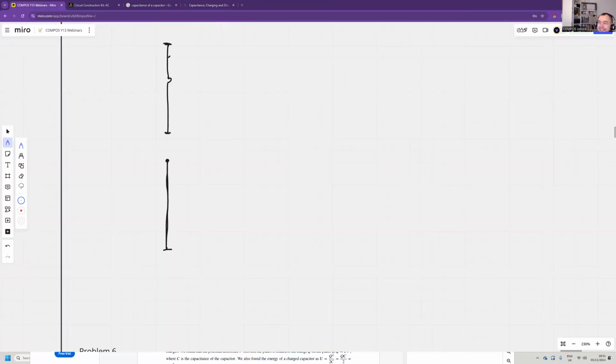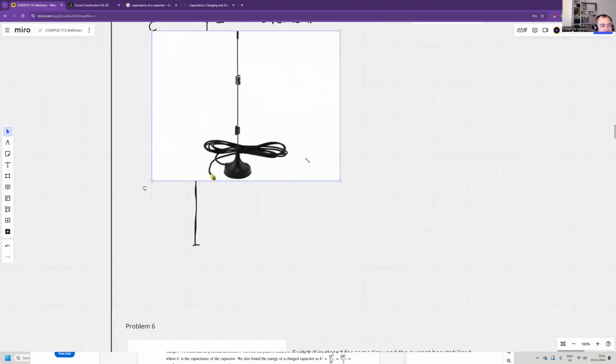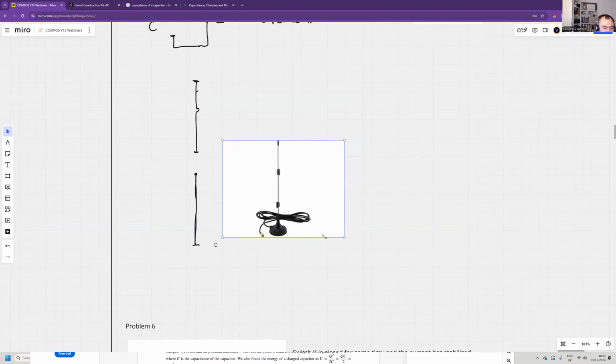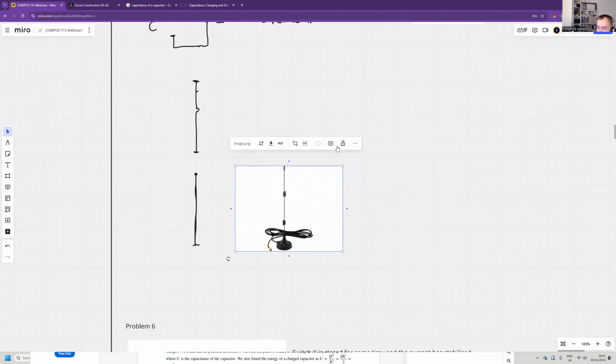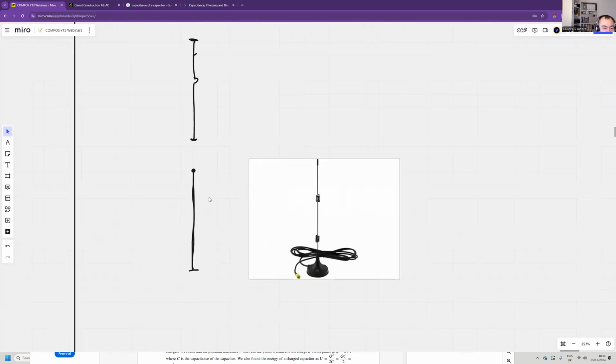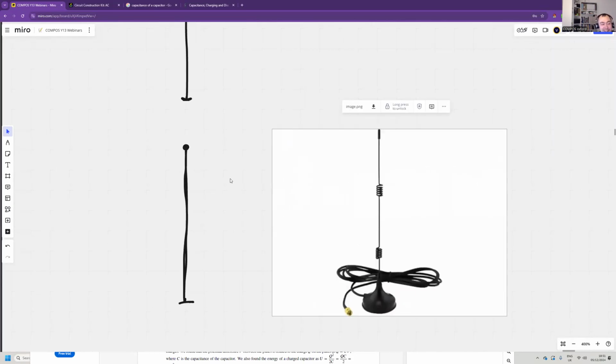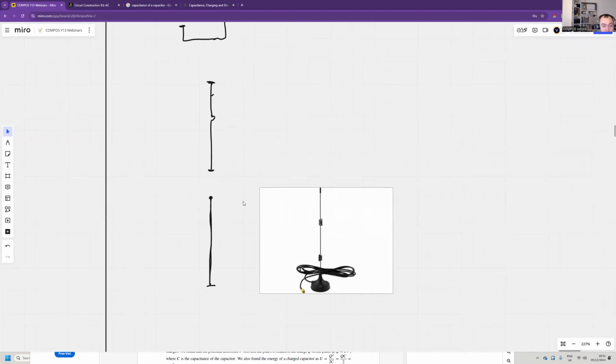Ooh, yes, Archie, you got it. Antenna. Of course, it is an antenna. Sometimes it even looks like this with an inductor. It doesn't have to be. Sometimes it's just a stick. But yes, an antenna. An antenna is an oscillating circuit, and the wire itself is an RLC circuit.